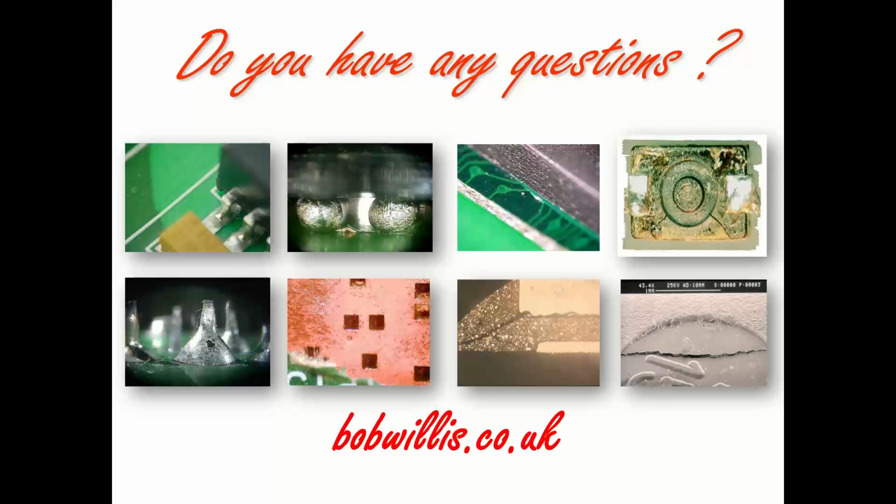If you've got other parts that you're going to reflow, like chokes, like relays, which some of the automotive companies do, like connectors, yes. But those parts generally are not defined by their supplier as being reflowable, and generally there's no MSD limit put on them because of that reason. So again, you've got to do your own investigation and understand yourself.